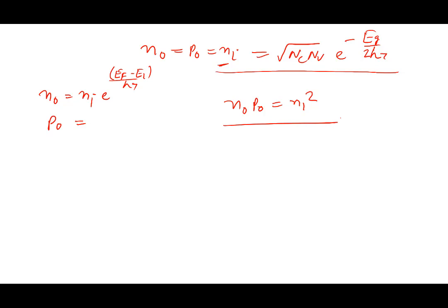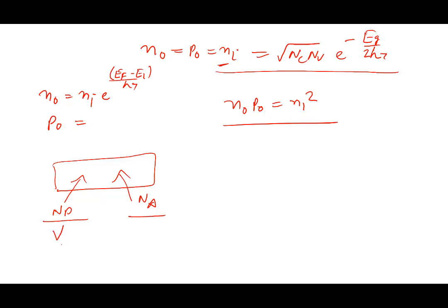Doping. All right, so we can dope. A pure semiconductor is not of that much interest. So we can dope, we can add an ND here, we can add an NA here. What is the insight from doping? So you add an impurity. You add a group 5 impurity, or you add a group 3 impurity to make it n-type or p-type.